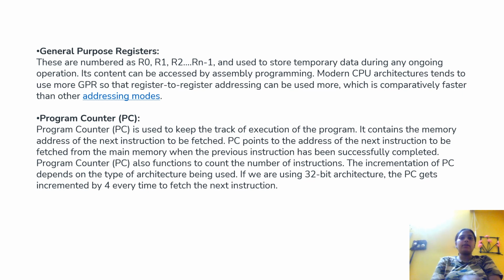has been successfully completed. The program counter also functions to count the number of instructions. The incrementation of PC depends on the type of architecture being used. If we use a 32-bit architecture, the PC gets incremented by 4 every time the next instruction fetch is done.